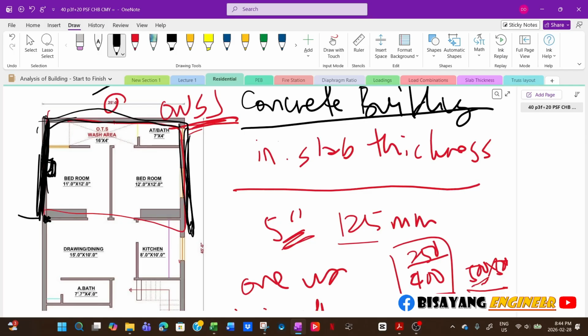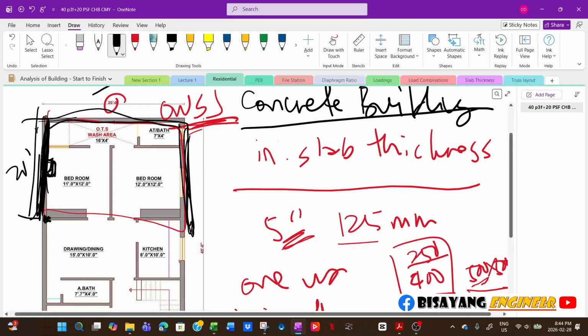So, for example, if this is 20 feet, then you have to design this regardless of how big it is. That's where, like I said, when you first start your calculation, you will have a conceptual framing plan, and then you run your first calculation, and then once you have the result, you talk to the architect: okay, this is what I got, and then it's up to the architect to decide. Or if for some reason you really need a column in here, then it will be the architect who would decide how to hide that one.